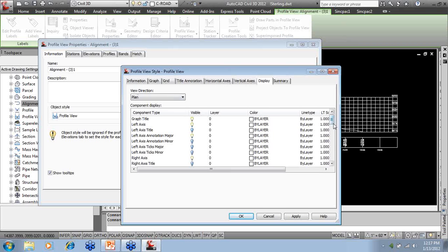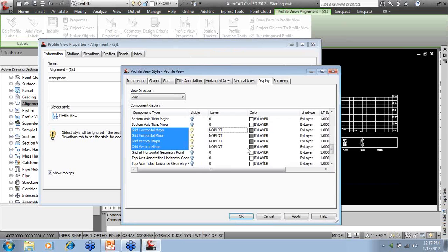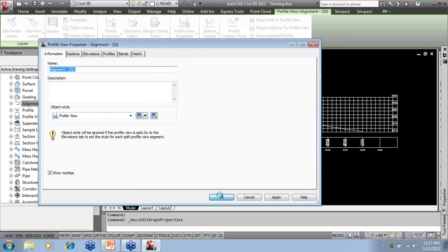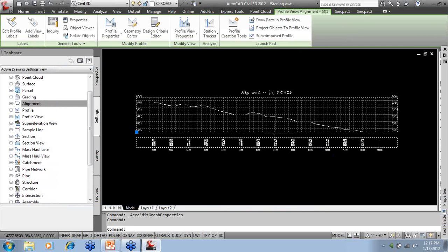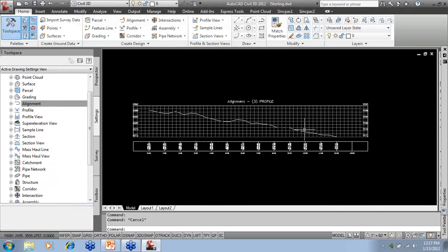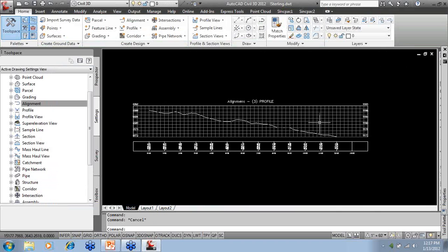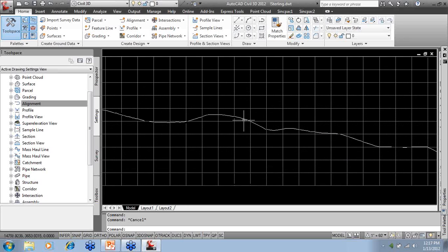This is all the tabs. This is the display tab. And maybe we want to go in and change the settings for these layers, put them on a layer grid, wherever you want to. What I want to show you right now is that if I assign this a layer and a color, it will update on the fly. These are almost impossible. You can see the gray there. Impossible to manage if you're hunting and pecking and you don't know what you're doing. So this is going to update. You'll see it update on the fly, and it's the best way to work with your data.